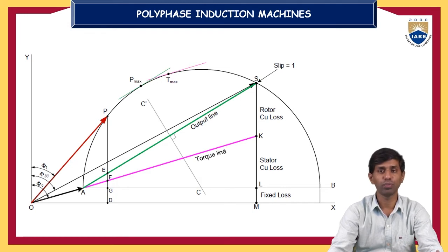That is, we have to measure the resistance of the stator with the help of either a multimeter, or you can also conduct a DC resistance test by connecting a simple voltmeter and ammeter. Generally, we know that is the volt-ampere method to calculate the resistance of any winding.